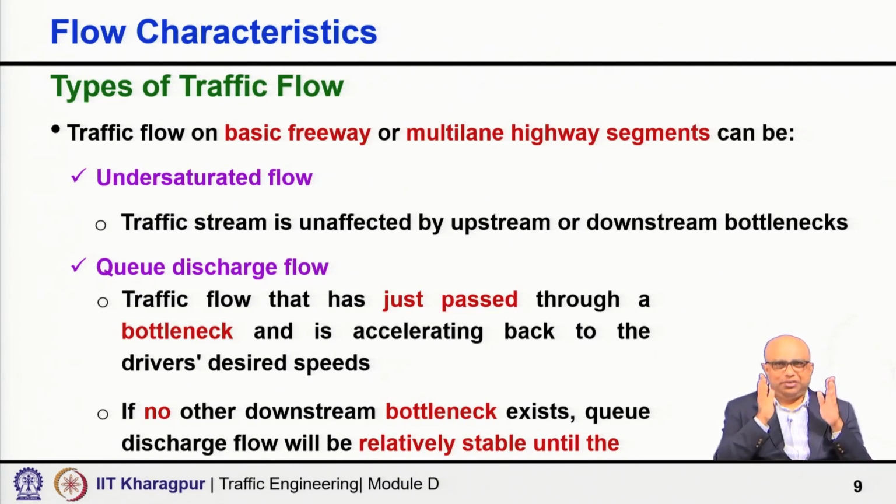Say you have a 3-lane road and then you have a 2-lane road. Now, if the demand coming from the 3-lane road is more than the 2-lane road capacity, then not all the flow can pass through this 2-lane section. So, there will be a bottleneck which will start at the junction of this 2-lane and 3-lane, at that boundary, and that accumulation of flow will occur and proceed towards upstream.